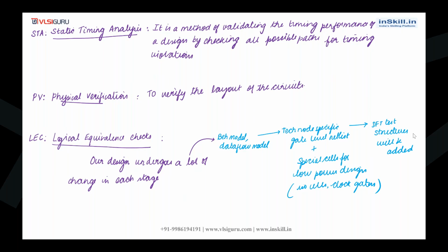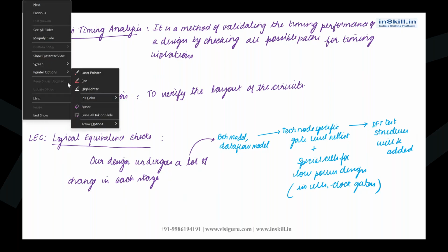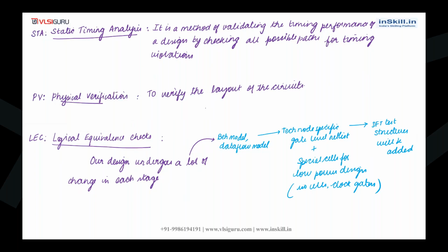So DFT test structures will also be added. If you see, our design undergoes a lot of changes in each stage. That is why LEC is done, to check whether the final design is logically equivalent to the original design or not.